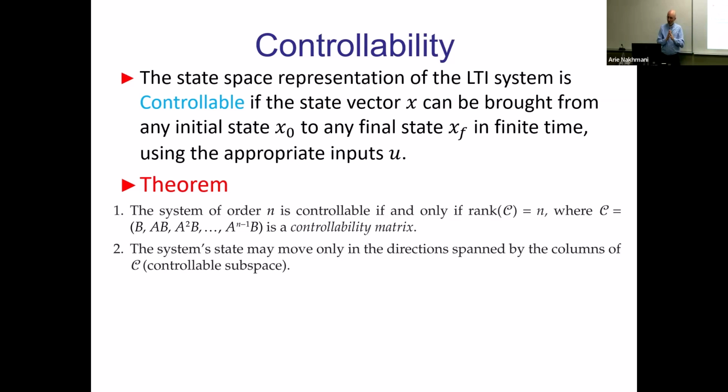If the system is not controllable, then it generates new kinds of issues. So if the system is not controllable, it still could be stable or stabilizable, but you cannot move all of the poles. You can move only a subset of the poles. All of the poles which will be canceled with zeros in the transfer function, you cannot move them because they are canceled, and this system will not be controllable or will not be observable.